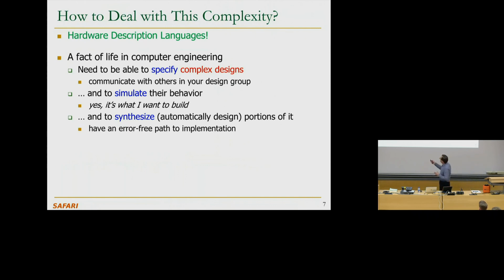So, but if you can do the synthesis, then you can also hopefully automate it, and make sure your synthesis tools are really good and bug-free. As a result, you can go from the hardware description language to hardware without bugs. That's actually nice. In modern processors, the cutting-edge processors, a lot of the parts are automatically synthesized like this. There are some parts of the circuits that require very custom logic, where the designer needs to go in and actually lay out the logic themselves, because those are very performance critical.